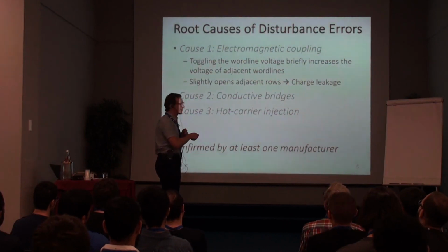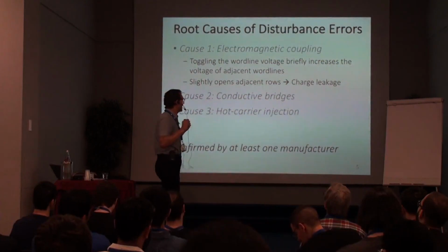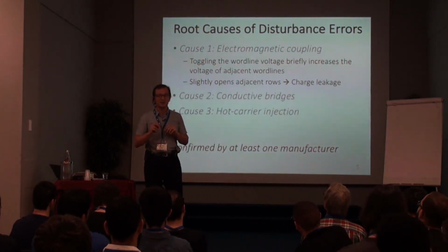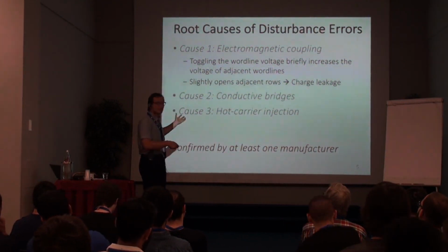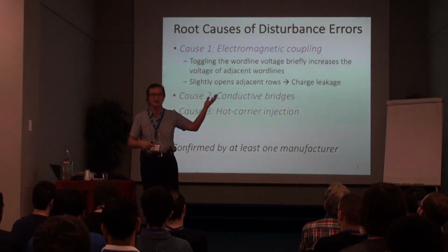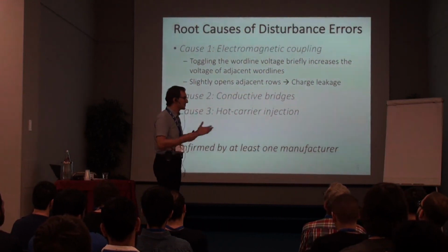That's one explanation, but it's really a combination of multiple effects, and it's really fascinating when the circuits become smaller. You get these really interesting noise phenomena that lead to errors. Conductor bridges are another of them. These conductor bridges get formed between circuit structures, so you get conduction paths that you don't normally expect because of the design of the circuit.